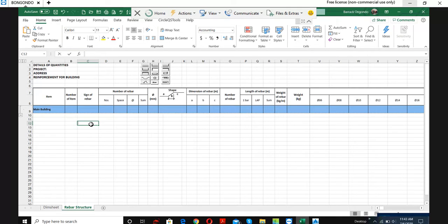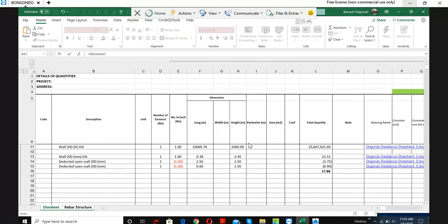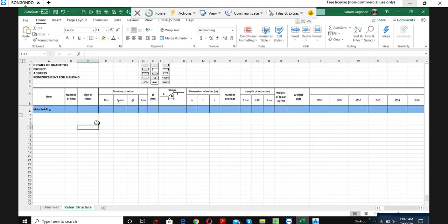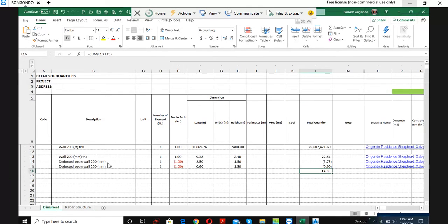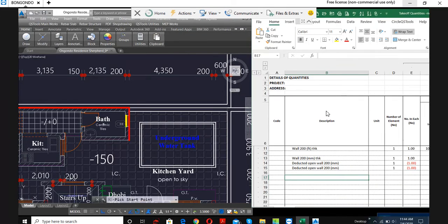So you just come here and say equals, you go back to your takeoff sheet, equals this, you enter. When you enter now, you see your BOQ quantity is already catered for, and then it applies a rate and gives you the amount. That's how you do it for all your walling. Generally, all the items of measurement that you're going to do, that's how you do it.